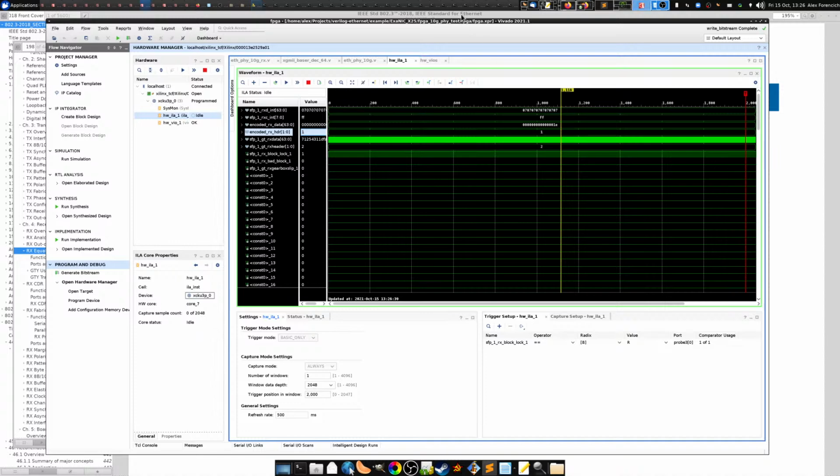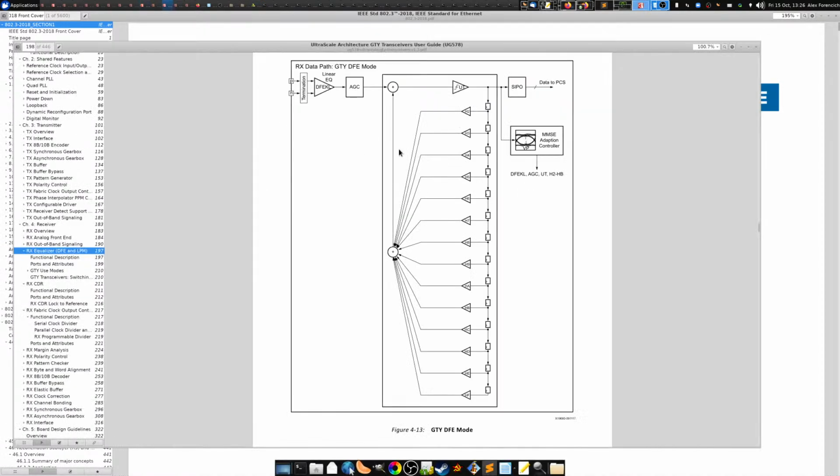Right, so that seems pretty straightforward, right? When it gets stuck like this, the problem is most likely coming from something inside the transceiver, presumably the DFE, but maybe there could be something else going on. And what you need to do is reset it. Okay, cool. So how do you know when to reset the transceiver? That's the trick now. Okay, so to figure that out, I actually spoke with Xilinx a couple times about this to see, is this a common problem people have, and what's the general solution to that?